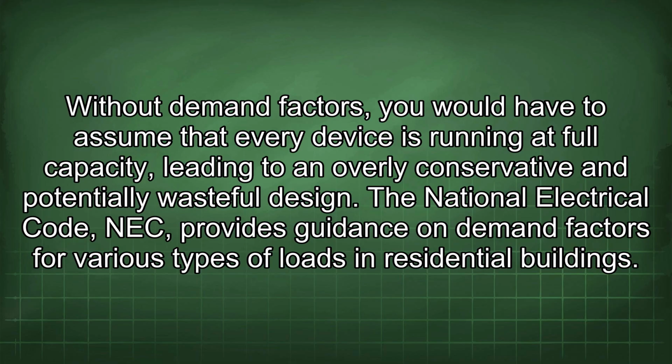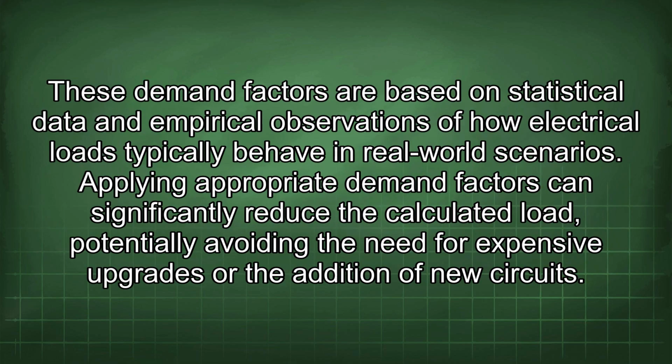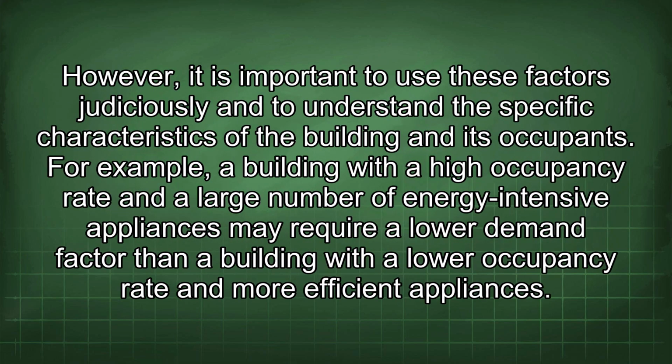The National Electrical Code (NEC) provides guidance on demand factors for various types of loads in residential buildings. These demand factors are based on statistical data and empirical observations of how electrical loads typically behave in real-world scenarios. Applying appropriate demand factors can significantly reduce the calculated load, potentially avoiding the need for expensive upgrades or the addition of new circuits.